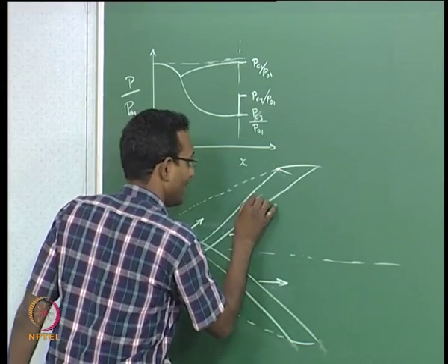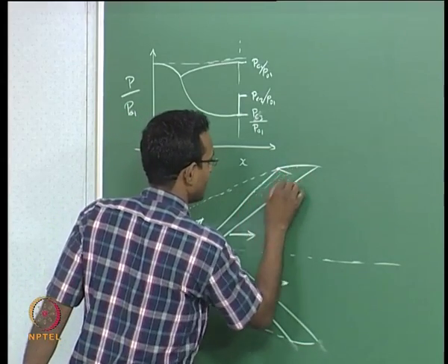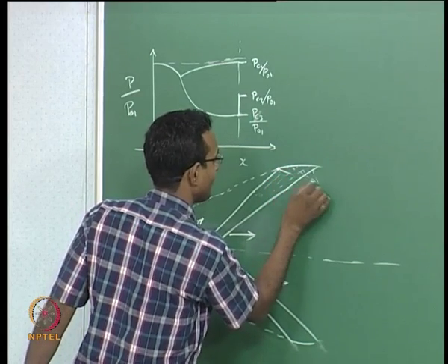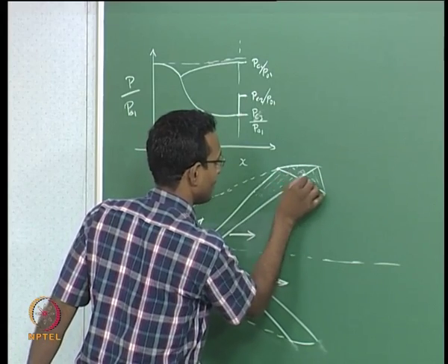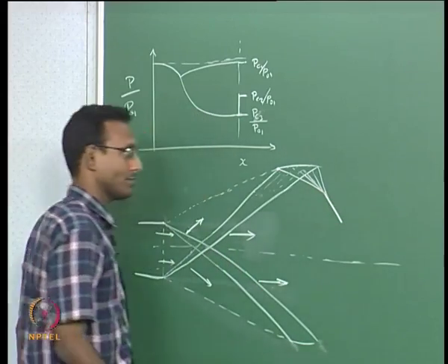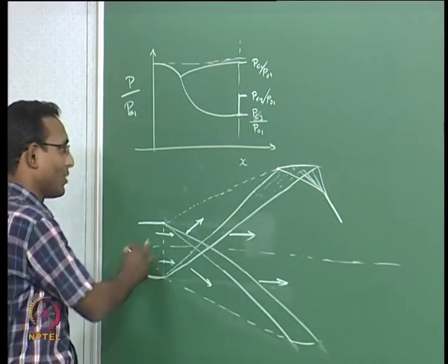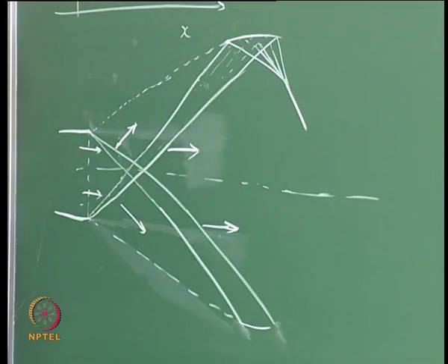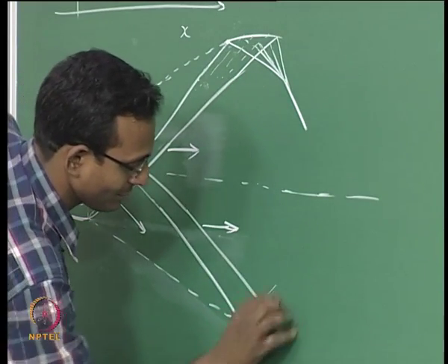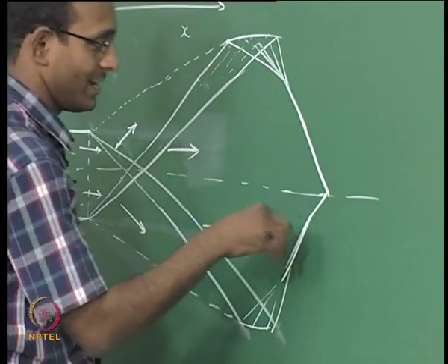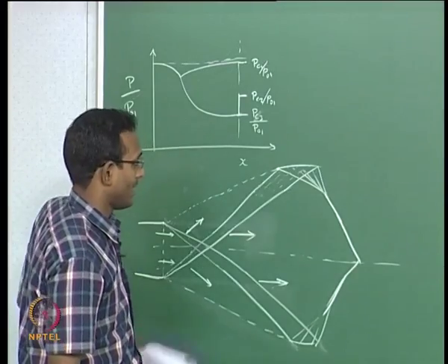Okay. Similarly, it will happen for all those expansion waves inside this expansion fan. Every one of them will send out one such thing, and a whole bunch of things together will eventually form one shock. It is similar to what we did last time, almost the same concept. It is going to go through this whole thing. Similarly, there will be one more coming from this side, and there will be a shock, and I am going to say these two shocks interact, ideally they should be symmetric, and after this we know what happens.